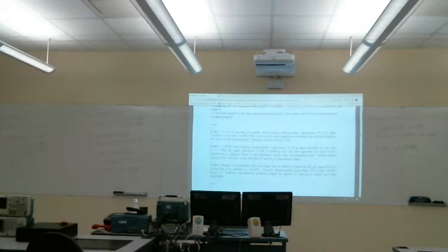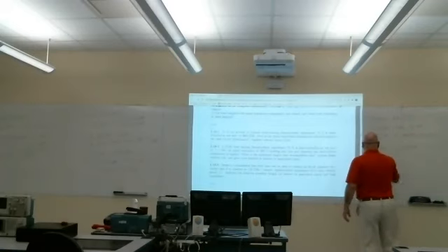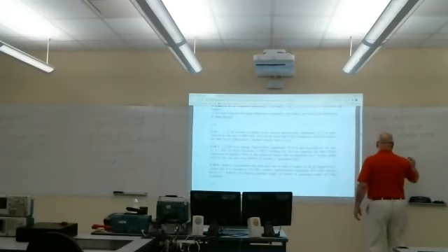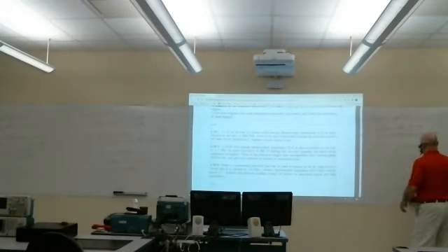The phase velocity is omega over beta, which implies that beta is omega over the phase velocity. So omega is 2 pi f, 2 pi times 900 times 10 to the 6.